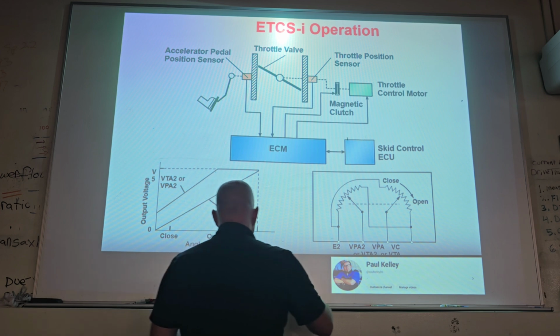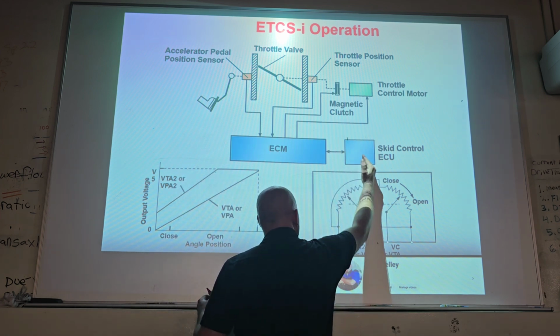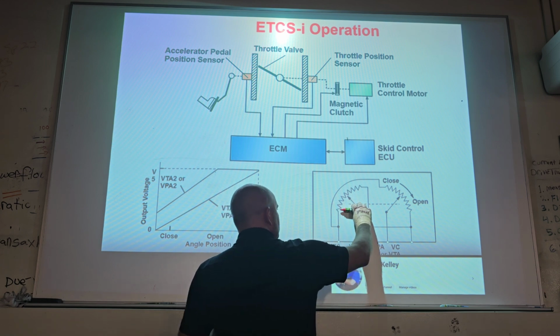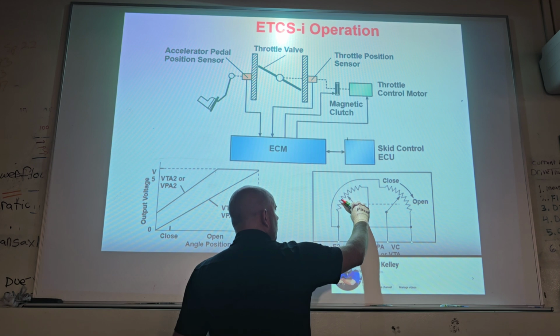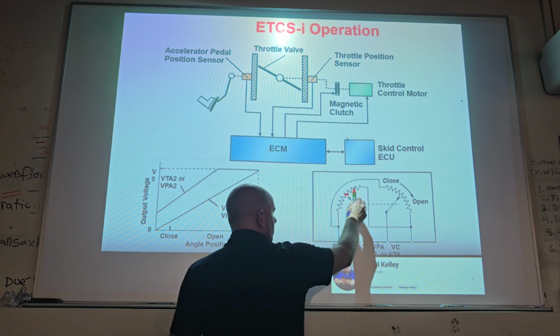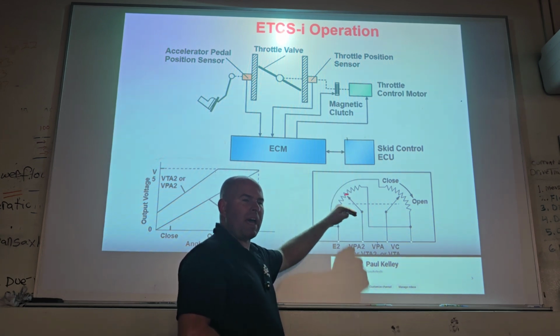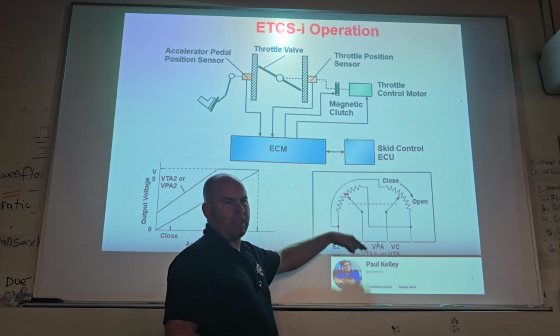So look, and this is skipping ahead a bit, but let's just say this is one throttle position sensor right here, okay? Just this side. This resistor is varying, right? So down here, a little resistance, more, less. But what if right here, there's a problem? It's like more, zero, more, maximum. See? So if there's a problem in that particular spot, it'll be a problem at that throttle percentage every time. And that one was 3.5 volts.